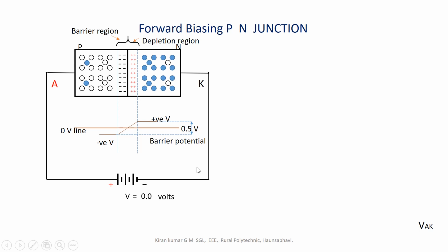Okay. Now, we will see the variation of the voltage between anode and cathode of this diode and the current flowing through this anode and cathode, meaning the diode, by drawing a two-dimensional graph, taking voltage across this anode and cathode along the x-axis and the forward current of the diode along the y-axis.